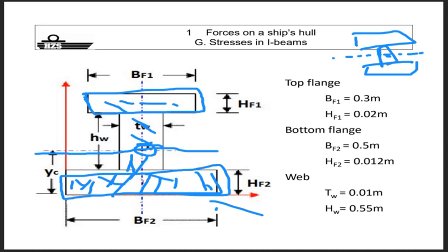Meaning that if soon you would like to calculate the maximum stress levels at a certain position along your beam, when you have calculated how your bending moments evolve, and you want to calculate your stress level. Suppose you have calculated your bending moments on that spot. Suppose you calculated the resistance against bending by calculating your moment of inertia around the neutral axis.